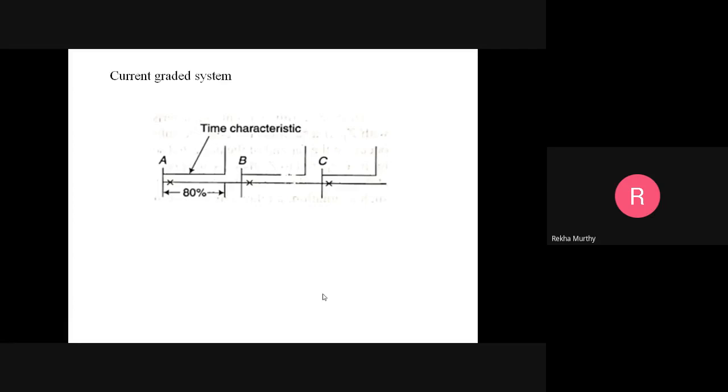If the fault current occurs at the end of section AB or in the beginning of section BC, that is one point. Second thing, the magnitude of the fault current cannot be accurately determined as all the circuit parameters may not be known to you. That is the second point. Third point is, during a fault, there are transient conditions and the performance of the relays is not so accurate. So because of these three reasons, we need to obtain a proper discrimination.